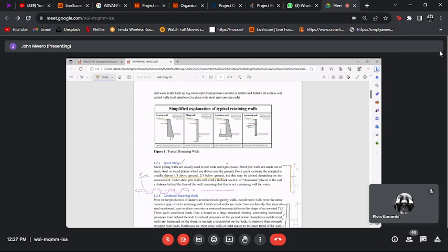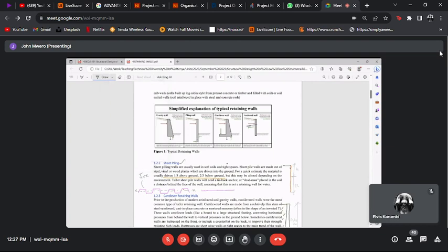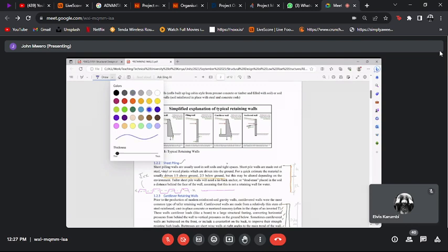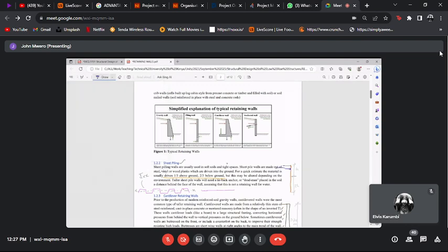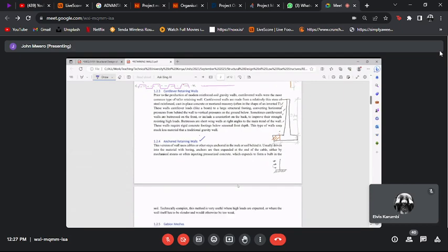And if you're not able to do this, there is an option of tying back this wall. So you tie it and you bury an anchor of some sort. Let me use a different color. So there's an option of tying back this retaining wall, and this anchor is referred to as a dead man. Okay. Now, if you do that, then you have an anchored retaining wall.